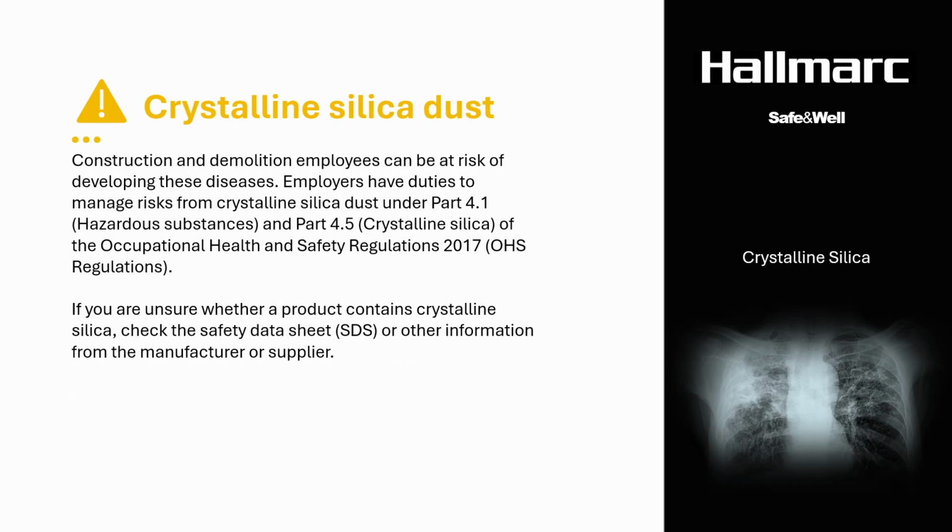Construction and demolition employees can be at risk of developing these diseases. Employers have duties to manage risks from crystalline silica dust under Part 4.1 and Part 4.5 of the Occupational Health and Safety Regulations. If you are unsure whether a product contains crystalline silica, check the safety data sheet or other information from the manufacturer or supplier.